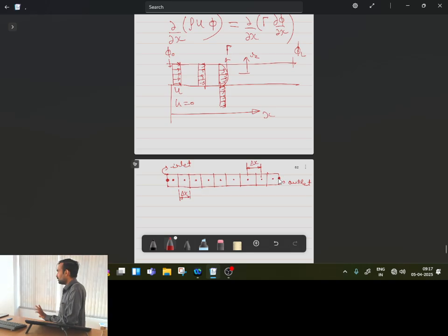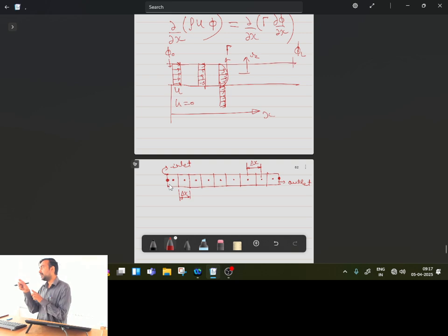Is this point clear? This is one additional thing which we typically do in the finite volume method, because whenever I define the control volume, the node point will be somewhere in between. So at the physical boundary of the domain, no centroid of the control volume will be occurring, but values will be available at the edges of the physical domain as boundary conditions.